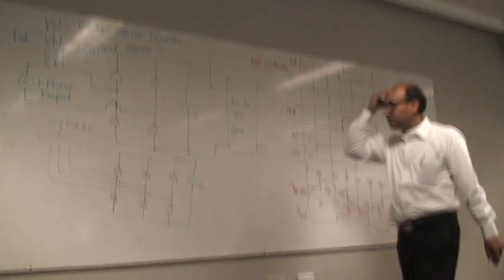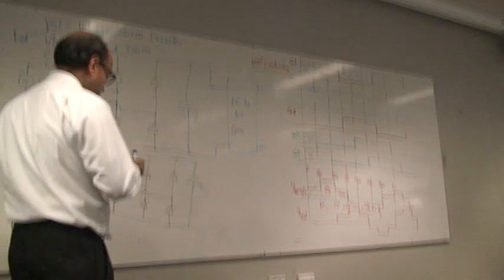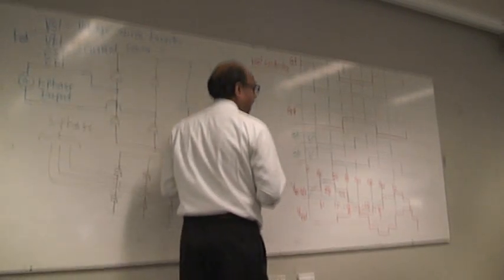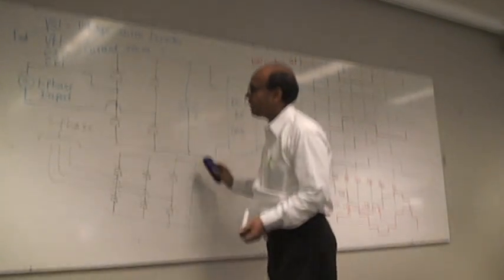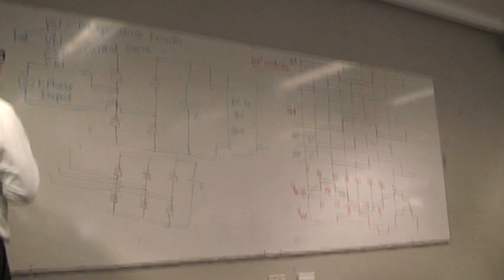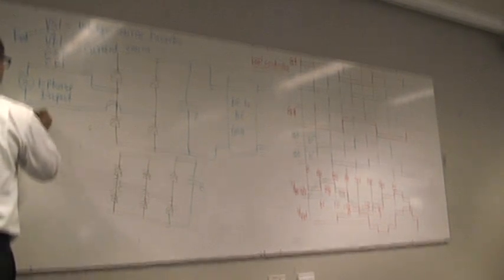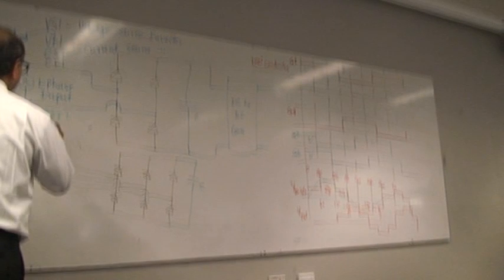So basically, I understand what you were talking about. But in practice, how do you actually do it? If you have a voltage source and you want to make it a current source, it's a very simple way. You just add a very large value of inductor. Predominantly that will make a current source. It's not a constant current source, but it's a current source.